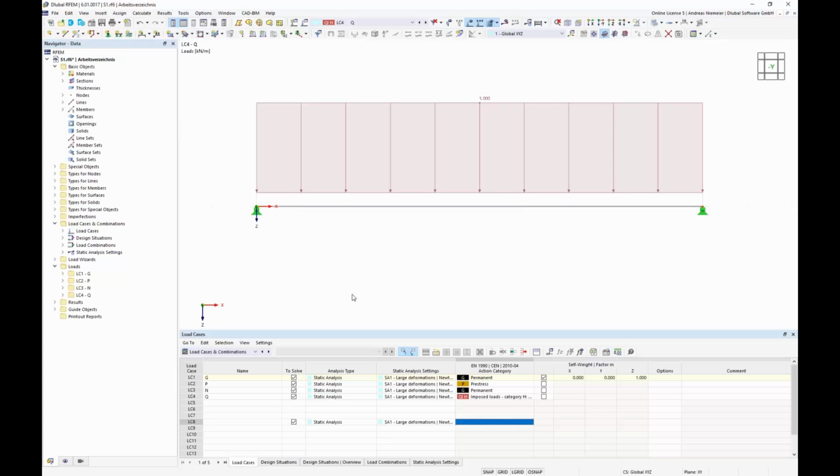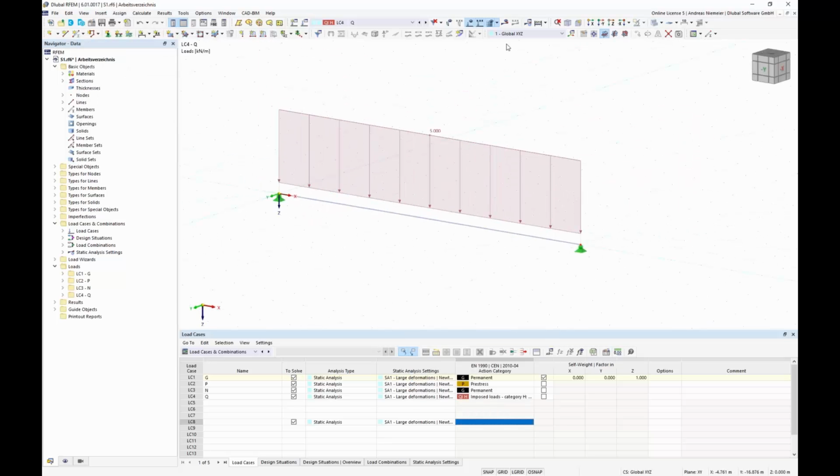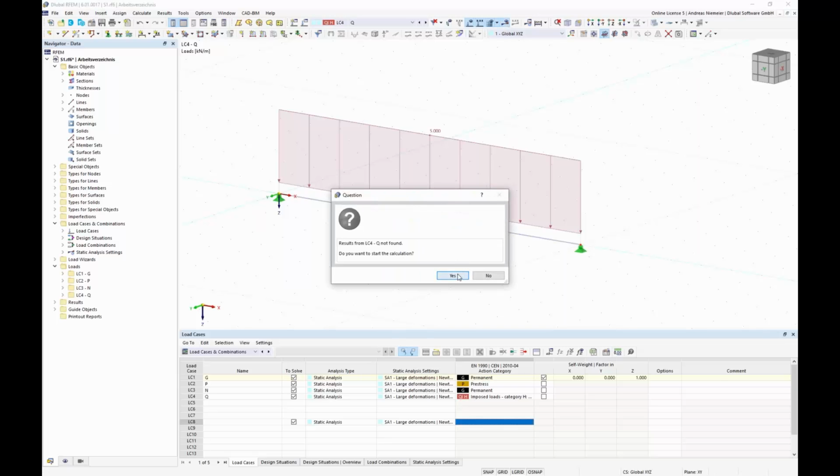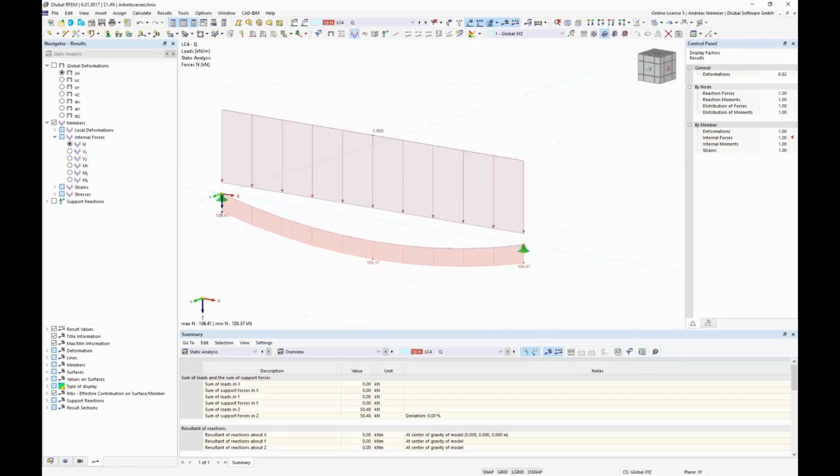So far we have a load on structure. If I run this load, what happens? Without any further specification, the program applies this load on the 10 meter long cable, yeah? And not in any shape. But if you want to apply it maybe on shape 1, you have to assign it.